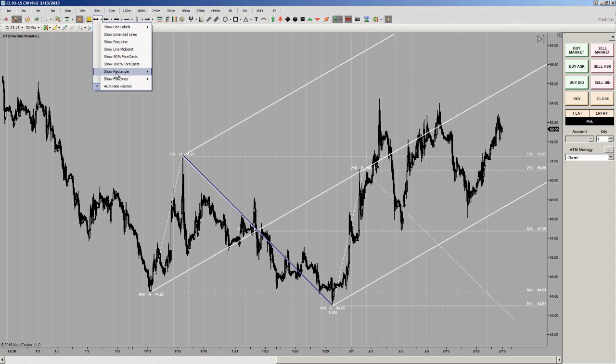And sometimes I get tired of, like what I just had to do since I had this set up to show all of this, to get back just to a line, I had to come up and turn each one of these on and off individually. I'm going to add down here at the bottom, turn all on, turn all off. That'll turn them all on, and then I can come up and probably not do the perpendicular line there, but be a quick and easy way to turn things on and off and get back.